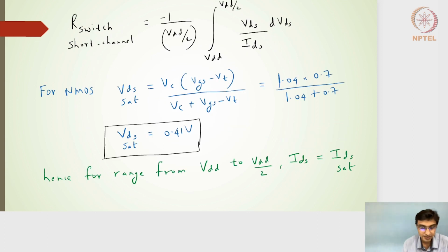So hope that is clear. Moving ahead, what is the switching resistance if I use the short channel current model? Now remember that the propagation delay falling using the short channel current model was somewhere around 10.86 or 10.79 picoseconds. So what we need is to benchmark this.